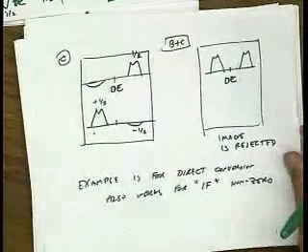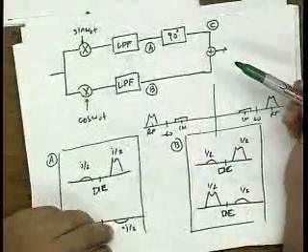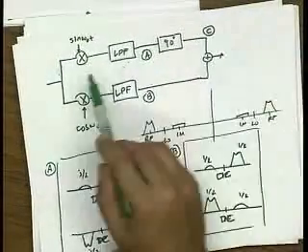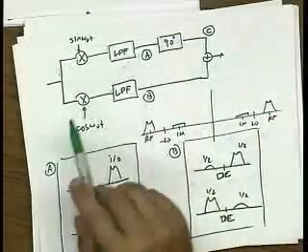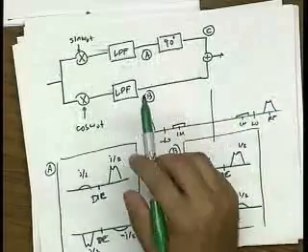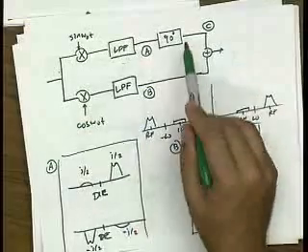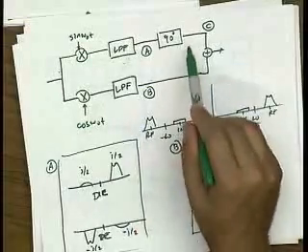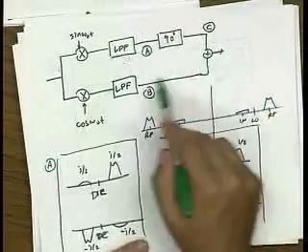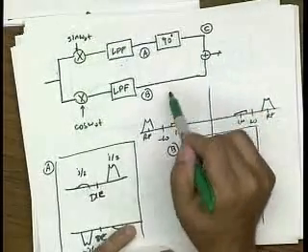Well, if you go back and look at this architecture and do this analysis, since we have a cancellation that occurs, it's very sensitive to the gain in each path and the phase in each path. Here, mathematically, it was easy to say that the gain is plus 1/2 or minus 1/2, or phase is exactly 90 degrees or minus 90 degrees. But in reality, if we build these with circuits, there's going to be an issue with matching the phase and magnitude in these two paths. So right away, you can see that this implementation is already asymmetric because one path has a 90 degree in it and the other one doesn't.